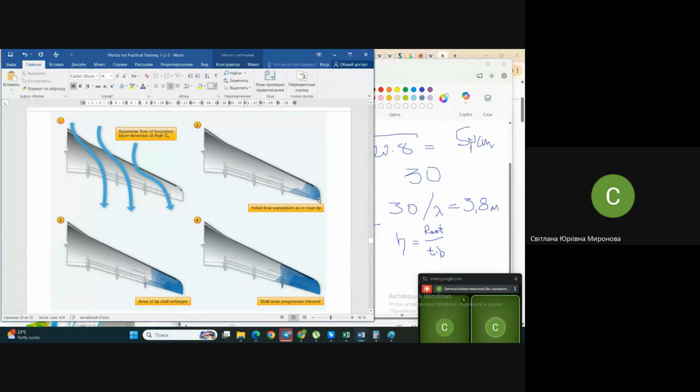On one hand, it's not good because here we have flight controls, ailerons, and closer to the fuselage, what do we have? We have high lift devices, which are not so important during cruise flight. You understand that high lift devices are practically used only during takeoff and landing. And the efficiency in cruise flight is not so dreadful for us, because they are not working here. They are hidden in the general profile of the wing. And ailerons we use during cruise flight, so not good.